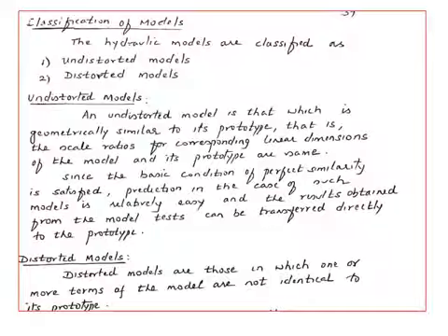So at that time you have to go for what is known as the distorted model, where the vertical scale is exaggerated. That means we give a separate scale ratio for the horizontal and another for the vertical, so that we get enough depth of water in the model, making it easy to measure.